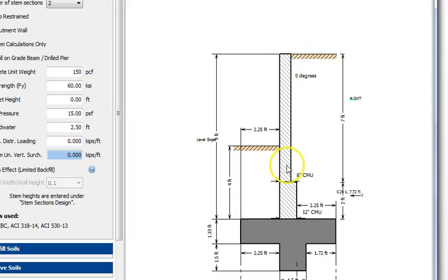So what we decided to do is use a 4-foot brace. That means you add soil in front of the toe. So now instead of having a 9-foot exposed retaining wall, you only have 5 feet exposed.